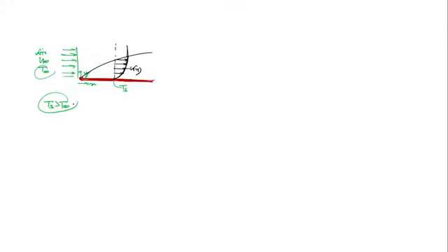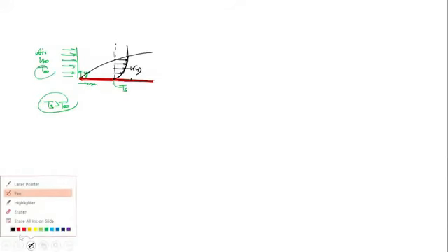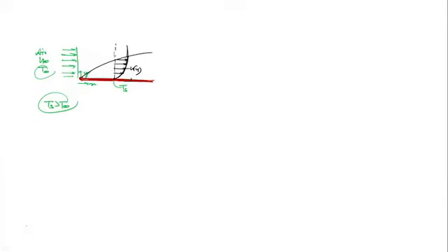Now as far as temperature boundary layer is concerned, temperature distribution is concerned, any fluid layer on the surface will have a temperature of Ts, and as we move away from the surface, temperature decreases like this. Let's say at this thickness temperature becomes 99% of T infinity, then this is called the thermal boundary layer. Two boundary layers have been formed, one is velocity and the other thermal. This is the thermal boundary layer, this is the velocity boundary layer, this is T as a function of y.